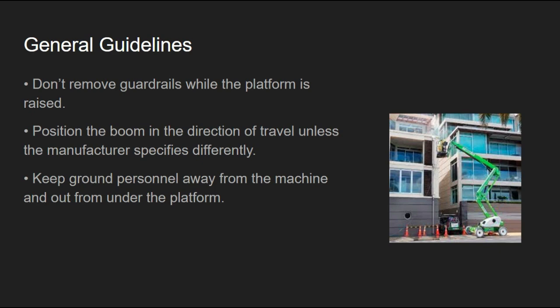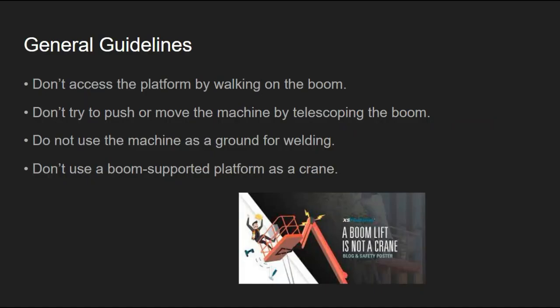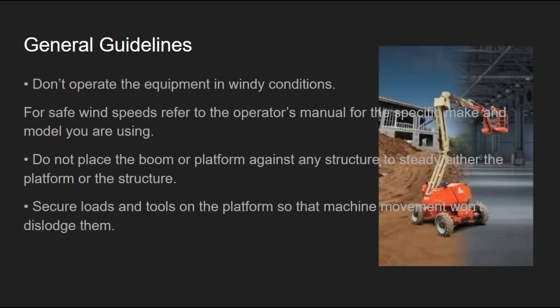Don't remove guardrails while the platform is raised. Position the boom in the direction of travel unless the manufacturer specifies differently. Keep ground personnel away from the machine and out from the platform. Don't access the platform by walking on the boom. Don't try to push or move the machine by telescoping the boom. Do not use the machine as a ground for welding. Do not use a boom-supported platform as a crane.